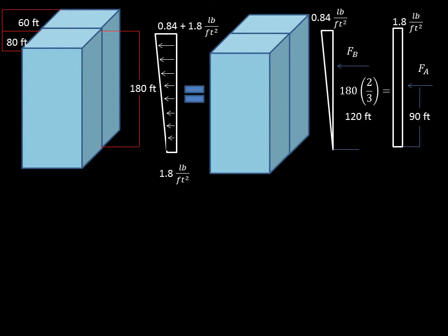First, let us analyze the triangular part. In this shape, when making it into a single force, we place the force in the middle of the x-axis, and at 2/3 of the height in this problem since the distributed load is vertical.